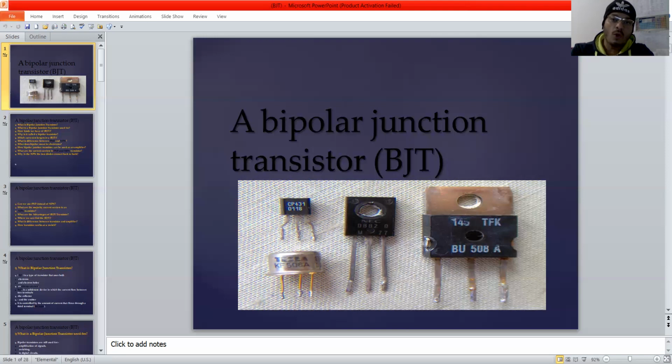How does a transistor work as a switch? Let's wonder about that. One of the most common uses of transistors in electric circuits is as a simple switch. Let's go deeper into the information. In short, a transistor conducts current across the collector-emitter path only when a voltage is applied to the base.